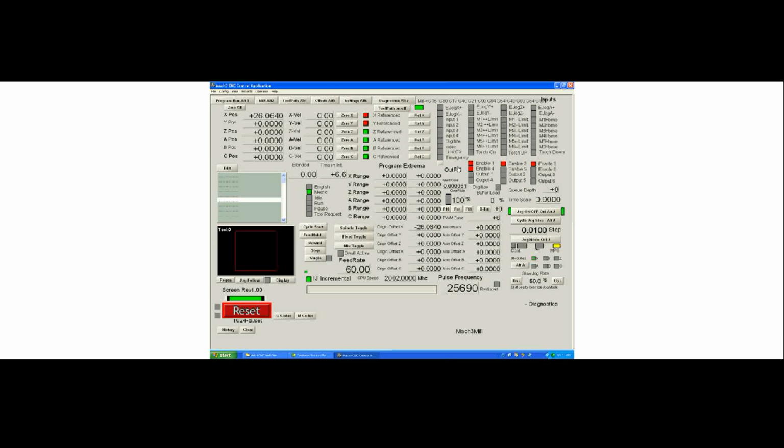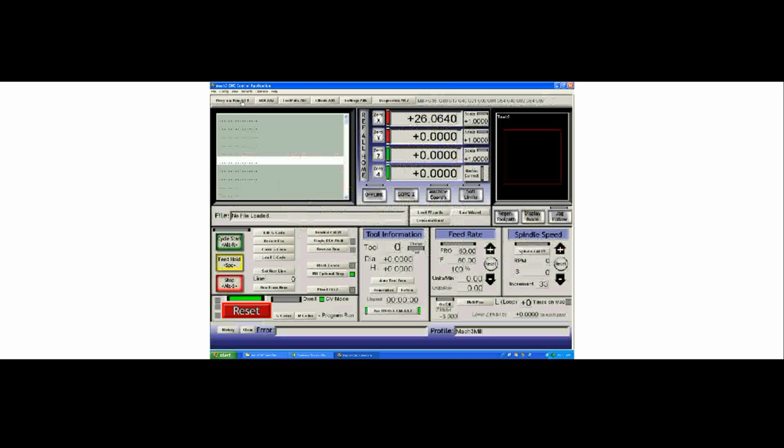state. Normally, the only thing you'll see flashing around when you're not moving is this time in interrupt DRO, which shows the number of microseconds that the driver is currently spending on each iteration through its interrupt cycle. I don't expect many of you to understand what I just said. Just take it from me that this number should be flashing, and it's quite normal. It should be less than 15 on all systems, and you can see mine flashes between about 6 microseconds and 4 microseconds, depending on how much housekeeping needs to be done at that particular interrupt. So let's go back to our program run screen.